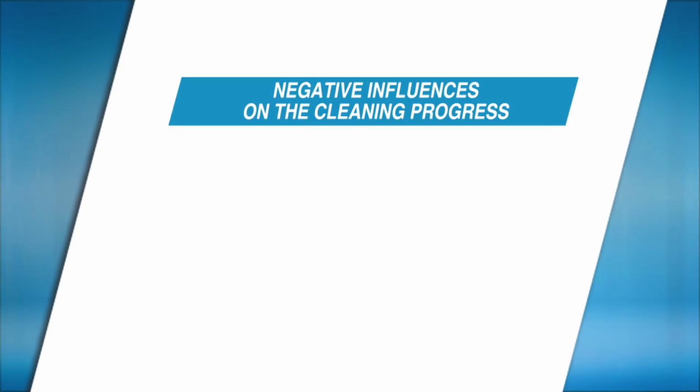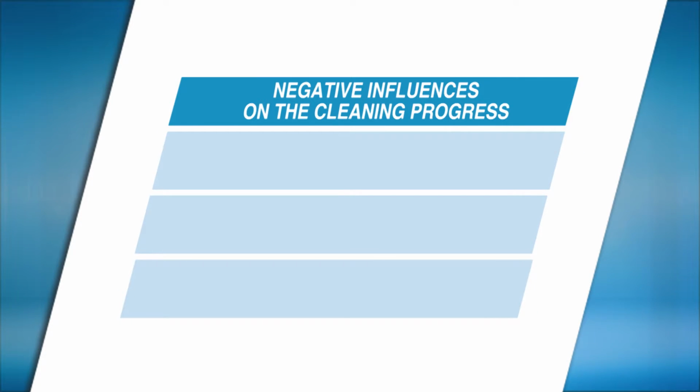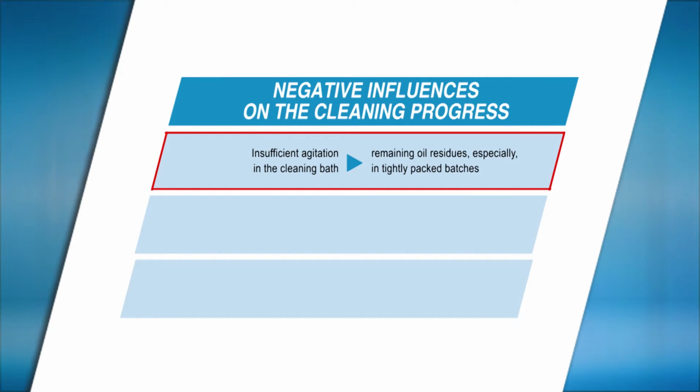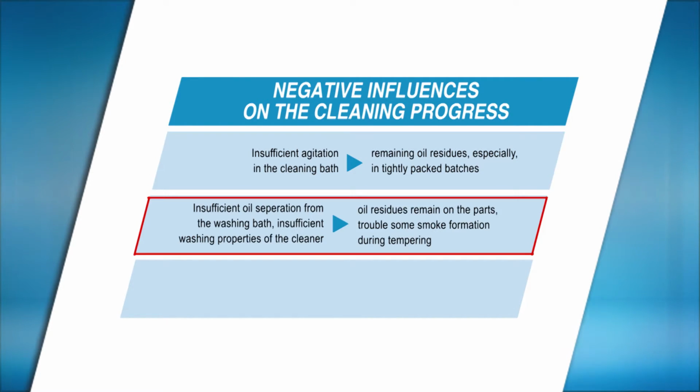It is essential to exercise certain precautions to avoid negative influences in the cleaning process. When agitation is inadequate, it may influence the cleaning of parts, particularly when the parts to be cleaned are immersed in the bath in a tightly packed condition. Care has to be taken to ensure oil residues on the parts are properly cleaned by the use of suitable cleaner, as otherwise these residues can cause smoke formation during subsequent tempering processes.